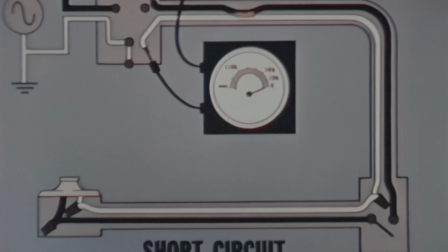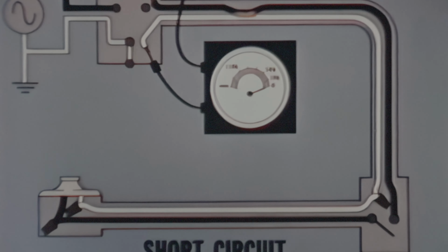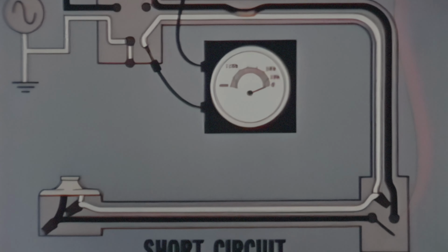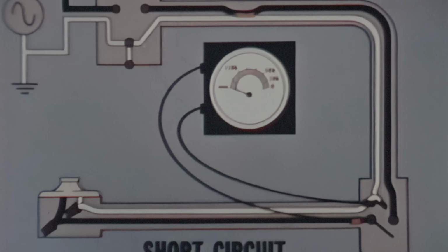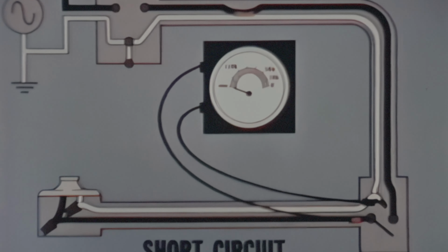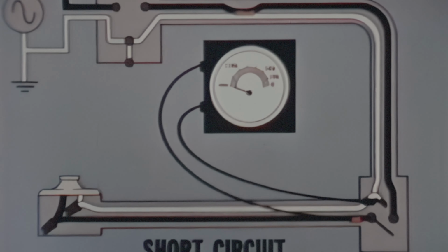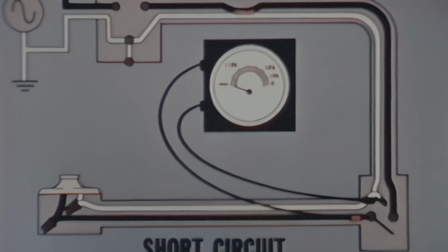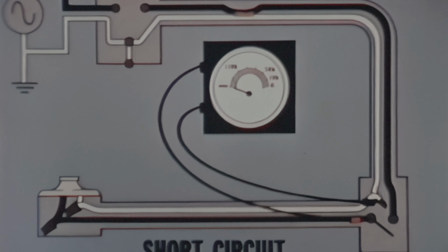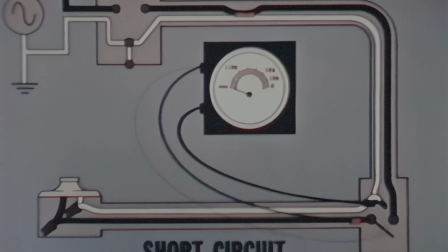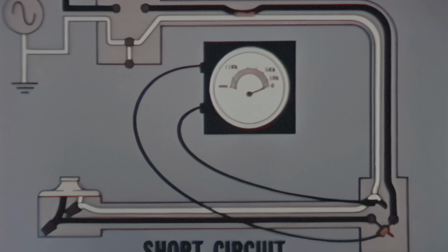Since the switch is open, the circuit problem must be in the length of conduit from the power source to the switch. To verify this, move the meter to the connections at the switch and check with the meter on both sides of the switch. On this side of the switch, the circuit indicates high resistance or no continuity. But on this side, the meter indicates the short. So the trouble has been identified and located.